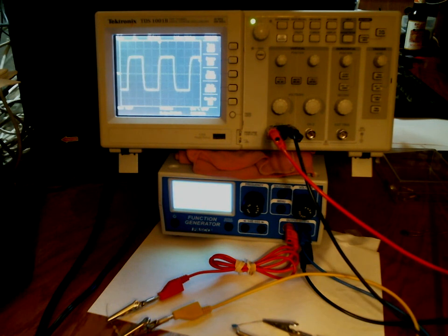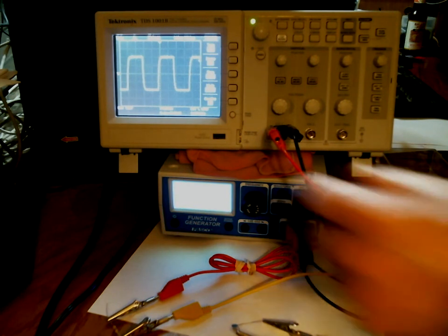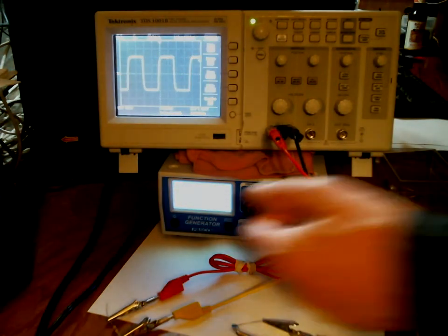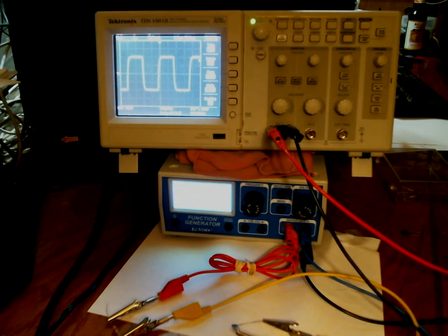And I think you can tell now that the exponential decay is a lot faster, but the period of the signal hasn't changed because the period is just set by whatever we set on the function generator and has nothing to do with the RC time constant of the circuit. So the faster exponential decay, you should now be able to figure out whether that means the new capacitance is bigger than the old one or smaller than the old one. Now let's go ahead and take quantitative data.